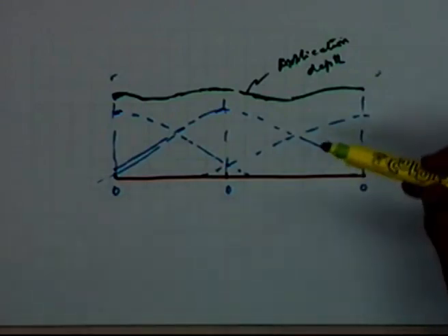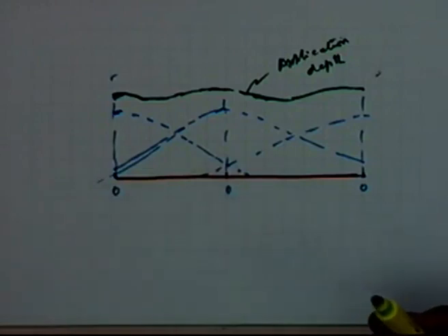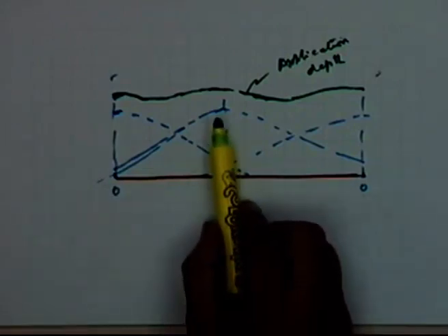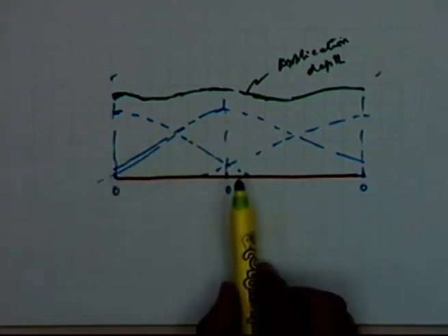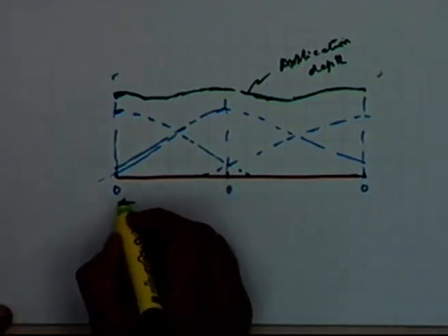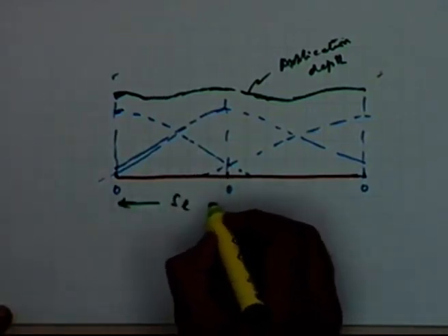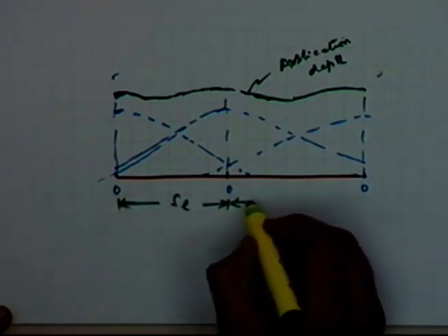The ultimate application depth is totally dependent on how these individual sprinkler head distribution patterns are overlapped, which is in turn a function of the spacing. In this case, this is the spacing between the sprinkler heads on the lateral.